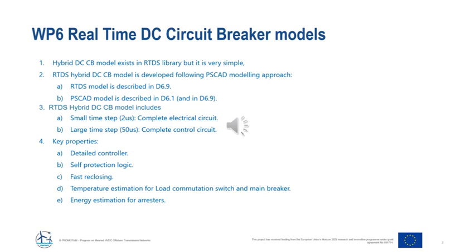This RTDS model includes a small time step part using a 2 microsecond model, which involves the complete electrical circuit, and a large time step part at 50 microseconds, which includes a complete control circuit.